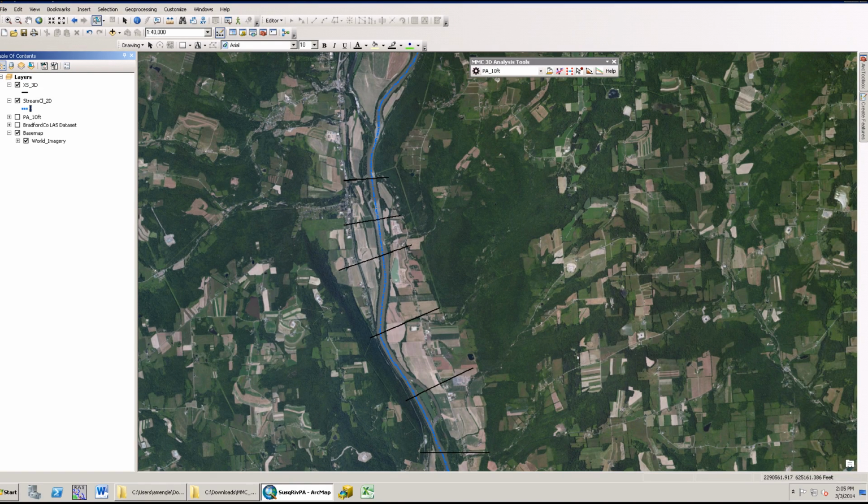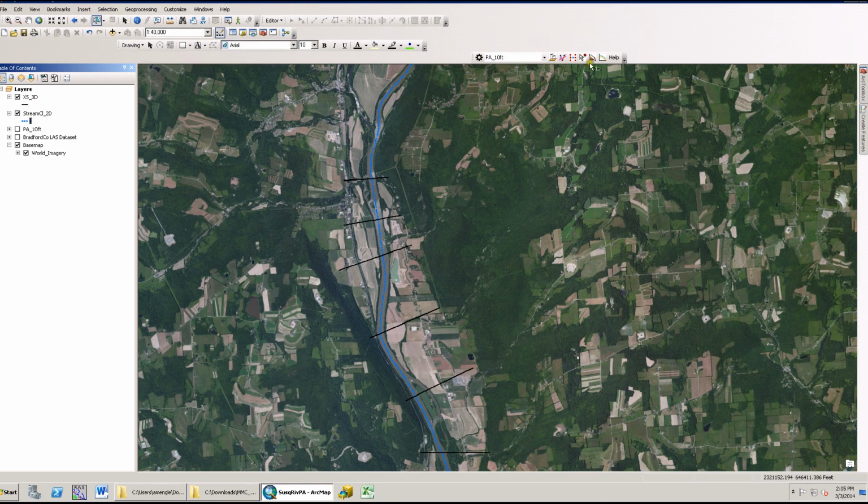This tutorial will demonstrate the Identify Measure Elevation tool found on the MMC 3D Analysis Python add-in. The Python add-in was developed by Gannett Fleming for the MMC Production Team. This tool will create a temporary point layer with the measure along a feature from a selected line layer in the table of contents. The line layer can be 2D or 3D. If it is a 3D line, this tool will also return the Z value.